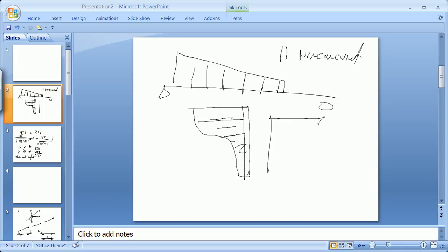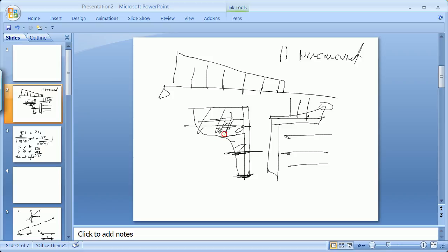It could be gravity on a cantilever, and wind, another distributed load this way. So there are going to be sets of parallel non-concurrent force systems that are distributed loads. And so if you understand that in any one of these systems you take the area underneath and you stick it there to get the resultant, but only do that for any single calculation, because as soon as you cut something there, all of a sudden you've got to recalculate the area and the centroid moves.